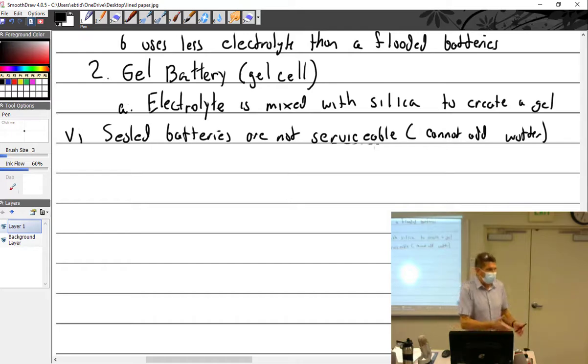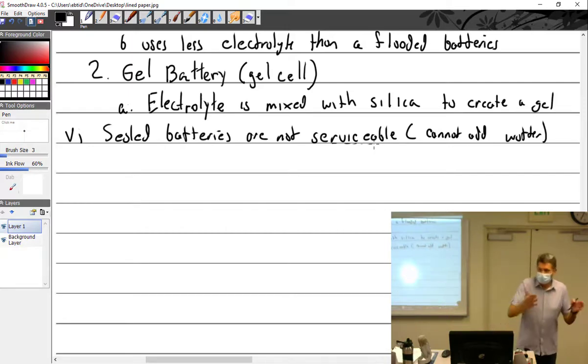When I first got into aviation, there really weren't what we call instructions for continued airworthiness, ICAW. It became a big thing somewhere in the late 90s, where everything needed ICAWs. Because what was happening is an airplane comes out of the factory with a manual that tells you how to work on it. But then you do something to it, a supplemental type certificate or a modification, and there were no instructions to go with it. So the next mechanic down the line would say, I don't know what to do with this. You modified it, and there are no instructions for what I'm supposed to do every year.